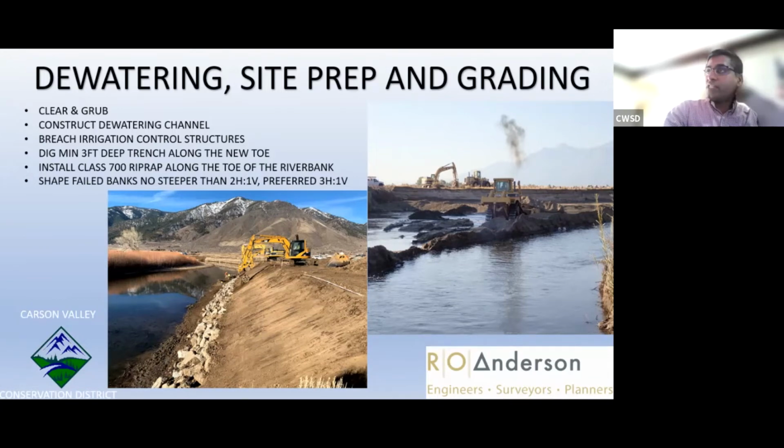We also had to breach some irrigation control structures. If you have been along the Carson River, you will see it was an Alpine Decree. They have water rights to divert surface water, and they have these irrigation control structures they install, and we had to breach those so that the water will just go downstream, so it's not too deep where we're working. And then when we're done, we'll just go back and fix those irrigation control structures.